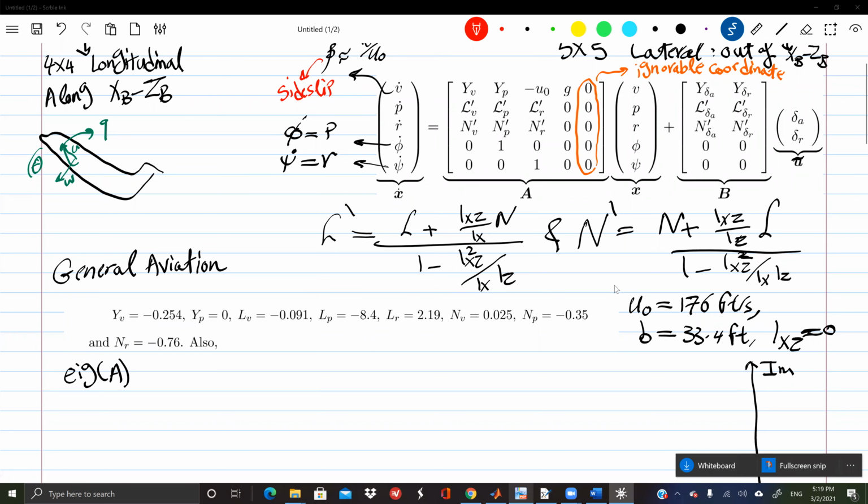So this is a good point, exactly like Jeremy was saying. If you have an unstable system, with an eigenvalue in the right half plane, and it's touched by any disturbance, it will blow up. If all your eigenvalues are in the left half plane and the system is stable, then if you're touched, the system will go back to its equilibrium. But if you have one eigenvalue exactly at the origin, and the system is touched, it will neither blow up nor come back to its equilibrium. So it will stay there, right?